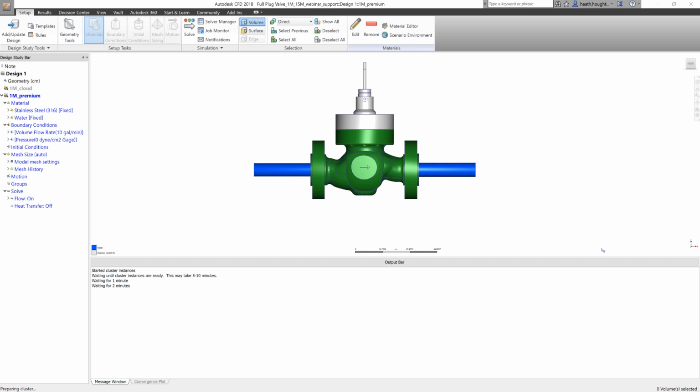And then the other question about the solution answers: what I've seen is that the velocity profiles and the temperature profiles will all look very similar. The main difference you will see is in the number of iterations it takes to get to the final fully converged solution. What we call solution control in the background is controlling how fast to move forward and still keep a solution stable, and how many iterations it takes.